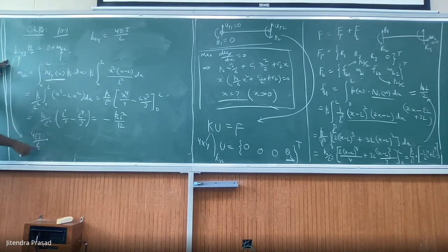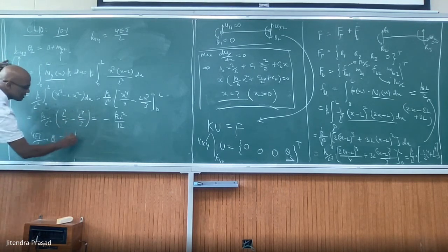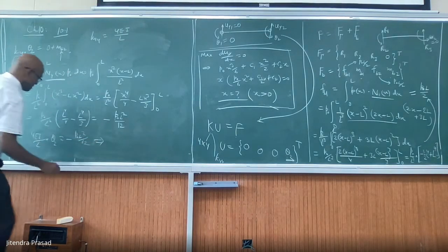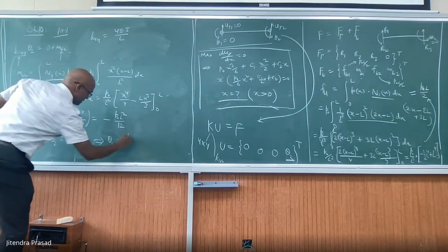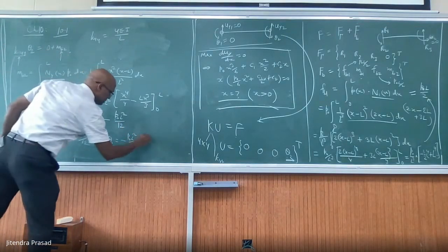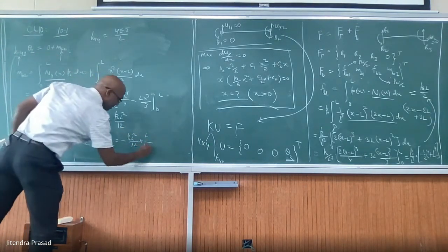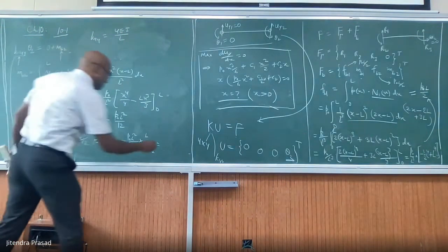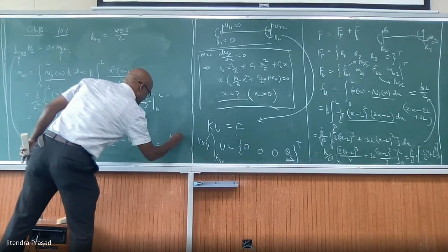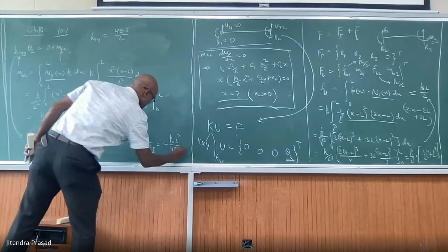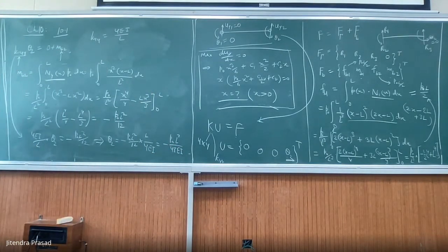Okay, now so this we got here. Then theta 2 is equal to MB2, which is minus P naught L square over 12, so theta 2 is equal to minus P naught L square over 12 multiplied by L over 4EI. So what do we get? Minus P naught L cube over 48 EI. So this is theta 2.